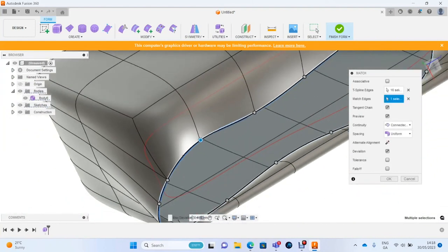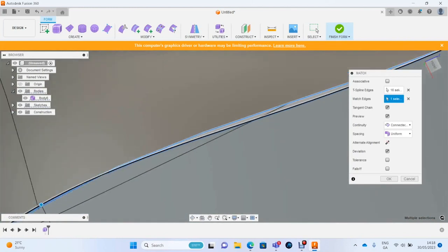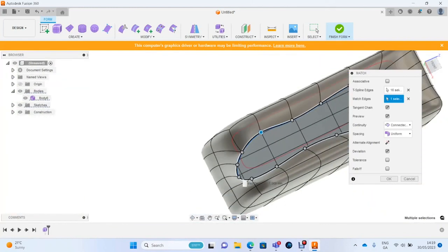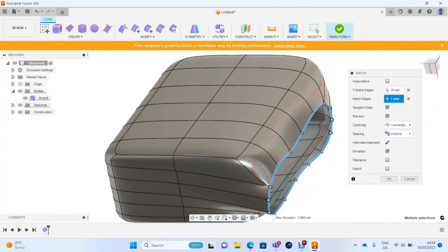It's never perfect, especially if I'm pulling to a spline. You're going to get gaps. And the way you would solve that is by increasing the amount of edges. You could subdivide these faces along here. We have different modes here that we can select through, and fall off as well.